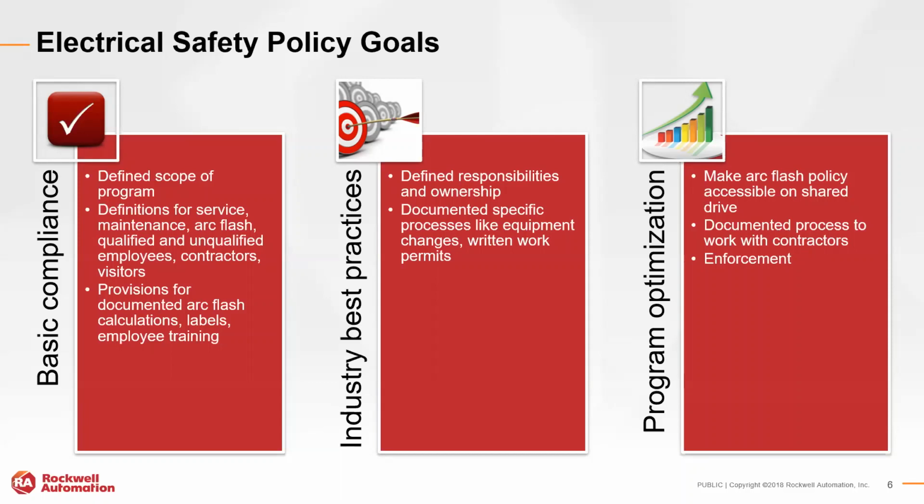documenting the specific PPE they're going to wear when they service energized equipment, based on the results of the arc flash study, things of that nature. So typically there's also an electrical safety program champion at a facility who will review that work permit that's been filled out with the qualified employee and sign off on it, in agreement that all the work steps documented are the proper steps to follow, so that that qualified employee is minimizing his risk while working energized as much as possible.